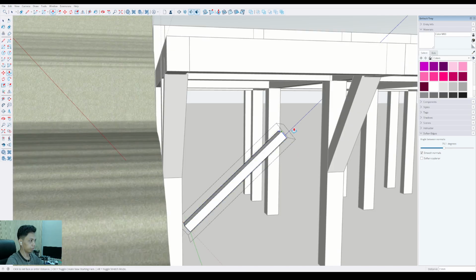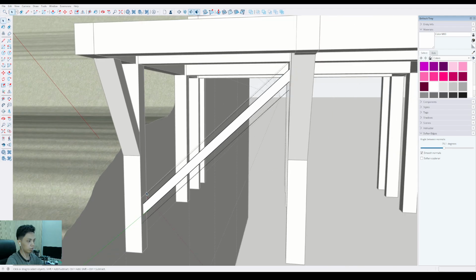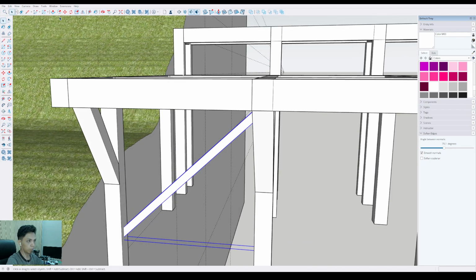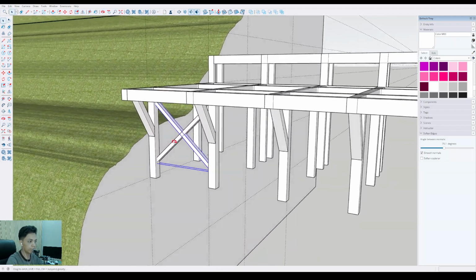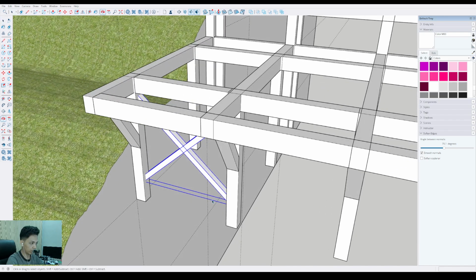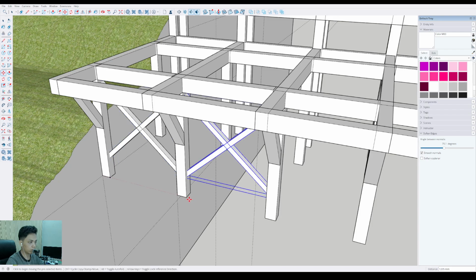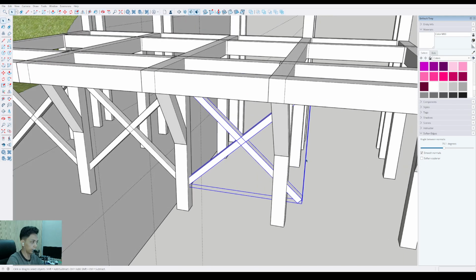Click. Okay, so you can place on this position. Then you can click, right click, and explode and make group, and then you can select a mirror. Then you can press Control, and then you can click the red axis. Okay, so you can get the result about it. So you can click and you can move and press Control to duplicate for every single grid structural system.